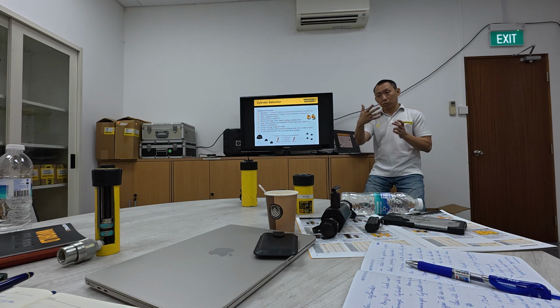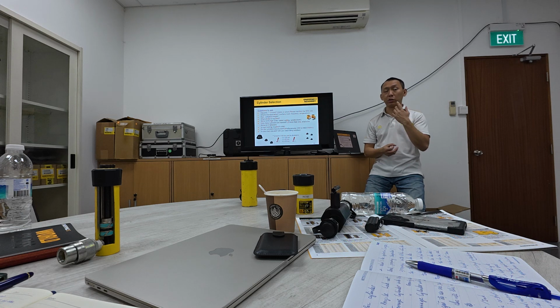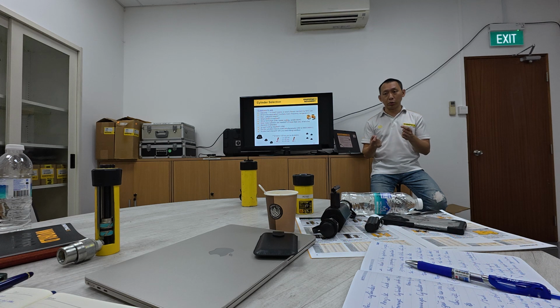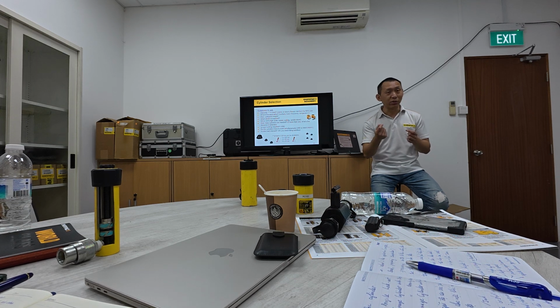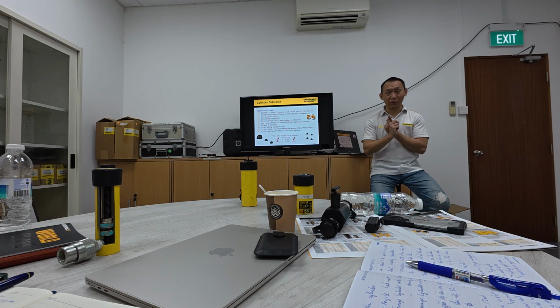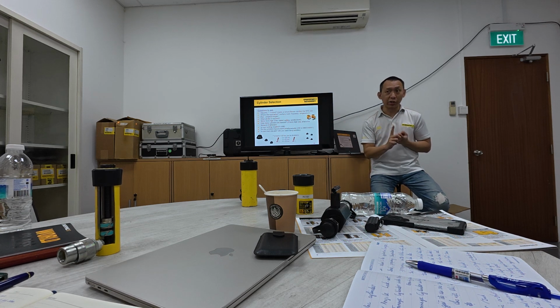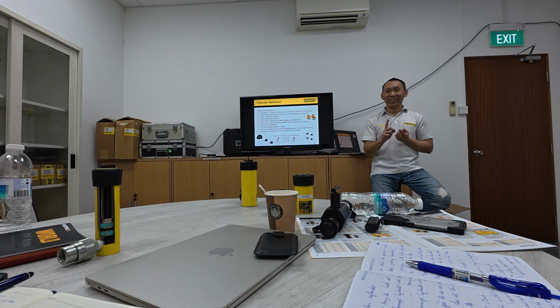So that one maybe it will work, but then again the wear and tear will be high also, because all types of seal, at that kind of frequency, will probably wear out faster. So it's very difficult for us to tell you which frequency you can use, because there are a lot of different pressures. If you are talking about every 5 minutes full stroke and retract, but at full pressure, that's a different topic. That one definitely wears out a lot faster because you are operating at full pressure.